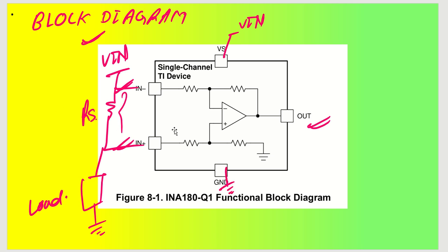And the advantage of a current sense amplifier is, if you want to use a separate amplifier, you will need gain setting resistors, like R1, R2, R3 and R4. So we will have the requirement of designing all these 4 resistors and setting the gain, and there may always be a possibility that, due to the tolerance in each of the resistors, there will be a difference in the output gain. Okay, so this becomes a little bit tough job. That's the reason they have been built inside the chip, and you are going to get a particular output. Okay,